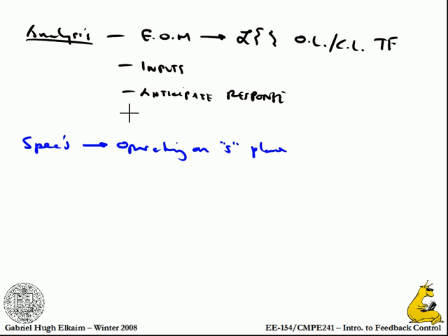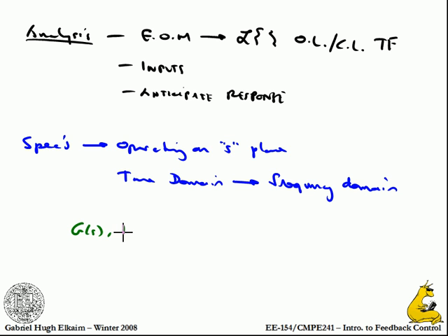So basically, given some time domain specs, I can now map this to the complex plane, get regions of interest, and start telling you sort of what the response looks like. And all of this works particularly well given a G of S and a K of S. I can do a reasonable amount of analysis here. It gets a little messy once we're beyond second order, but I can still do it.